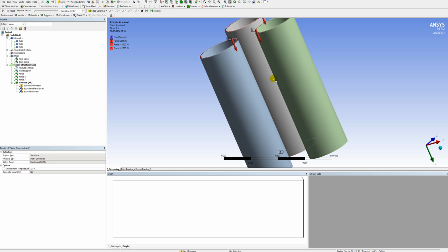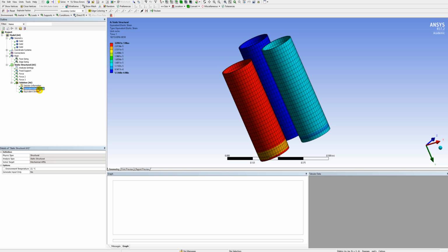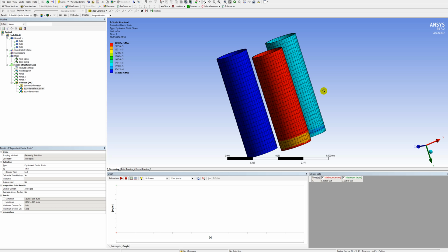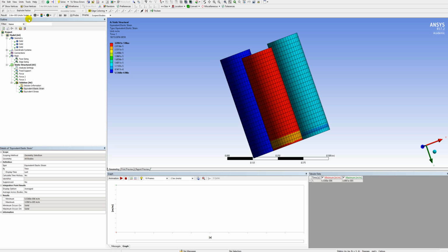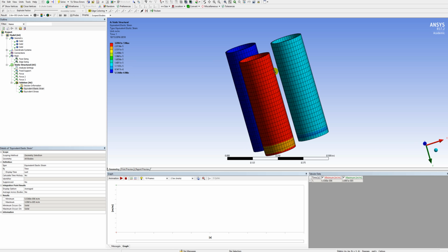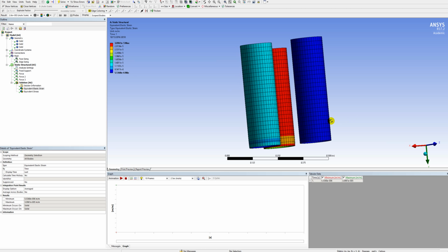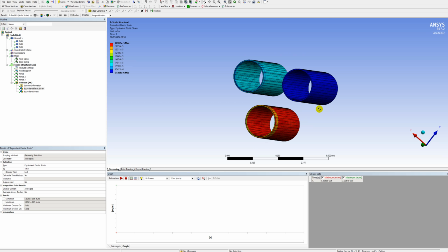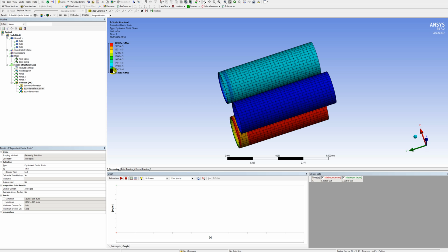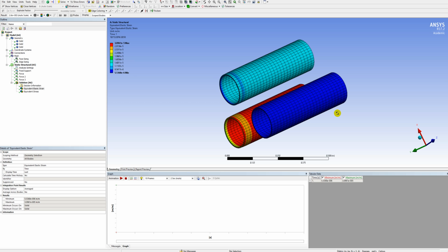Okay, after that's done, let's check the strain first. As you can see, the strain is different for each material, even though this is a different scale. This would be the true scale, and this would be undeformed. There's basically no change. Like it might have lengthened by 1 pixel. And that's not very much, even on a 4K screen. So let's go back to the auto scale to observe the deformation. Notice which one of the tubes deformed the least. If you check the scale, the least deformation will be on the blue tube.